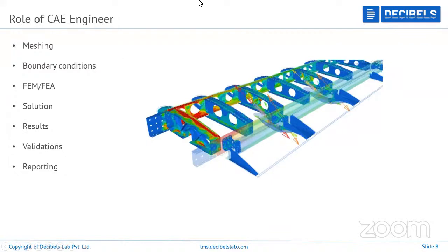After we get some results, we are going to plot them using any results viewer, for example, HyperView. HyperView is one of the products for visualizing and validating the results. Say for this component, I'm getting some stress value at the corner. By viewing only the results file, I may not come to know whether the results apply to certain 10 elements or 20 elements like that. So visually, I want to view the results, and I'm validating the results using some software.